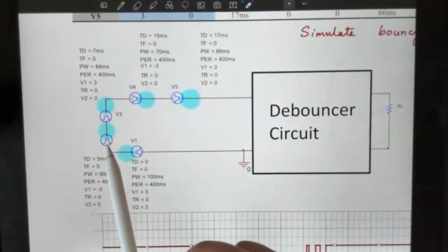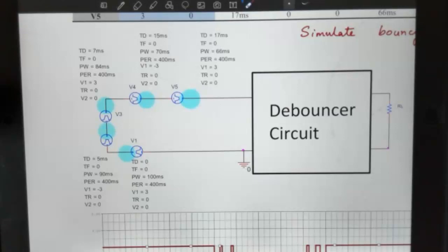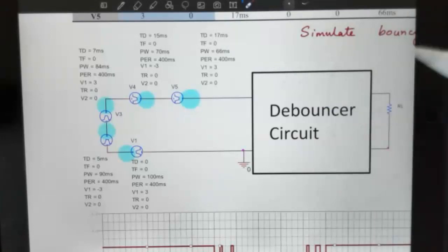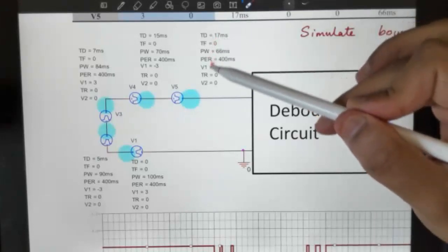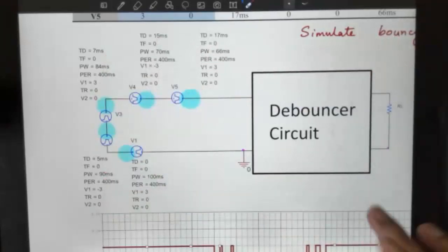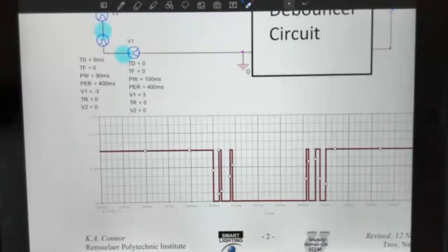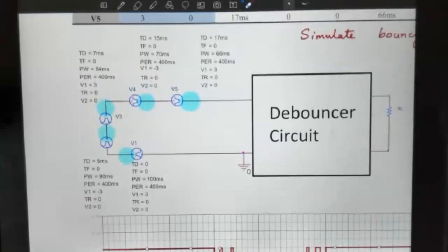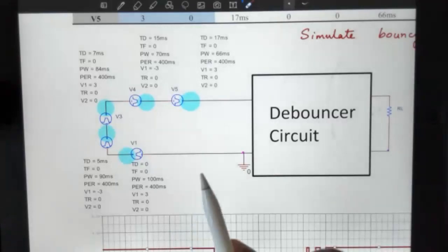So while building this, you need to keep track of the polarity of the voltage sources. More importantly, it is going to be very tedious to do this, but the numbers that you enter for each of these voltage sources are going to dictate whether you get a combined voltage effect of the bouncy switch or not. So make sure you double check, you triple check, you check several times what numbers you entered. I hope I've given you some ideas about the common errors there.